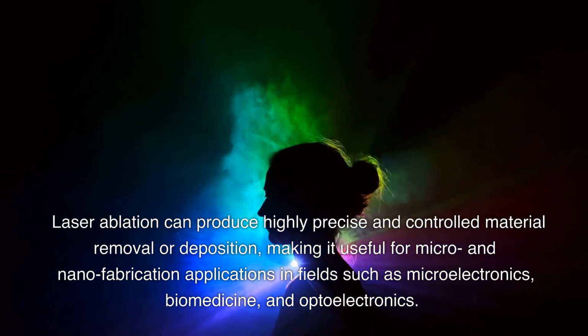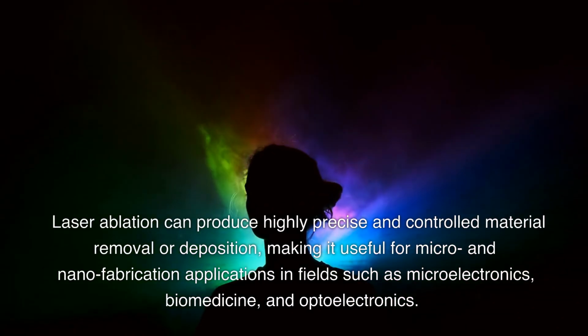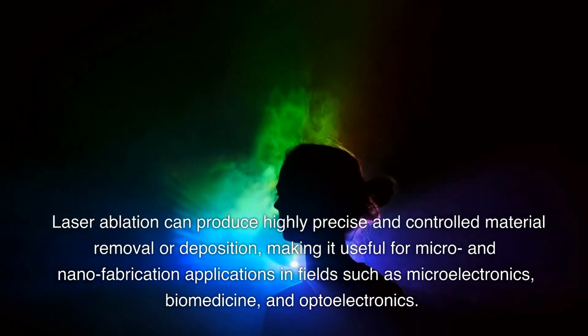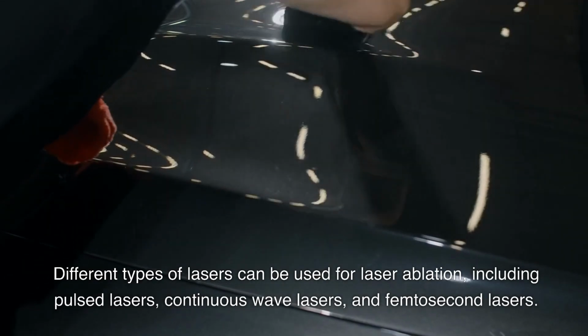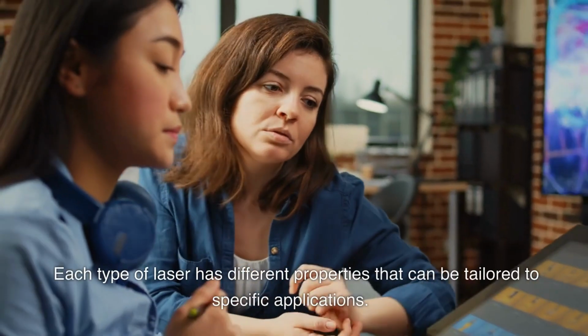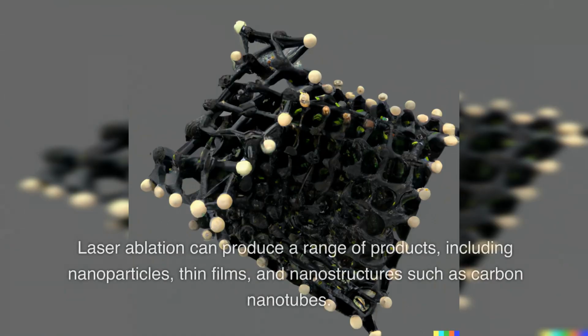Laser ablation can produce highly precise and controlled material removal or deposition, making it useful for micro and nano fabrication applications in fields such as microelectronics, biomedicine, and optoelectronics. Different types of lasers can be used for laser ablation, including pulsed lasers, continuous wave lasers, and femtosecond lasers. Each type of laser has different properties that can be tailored to specific applications. Laser ablation can produce a range of products, including nanoparticles, thin films, and nanostructures such as carbon nanotubes.